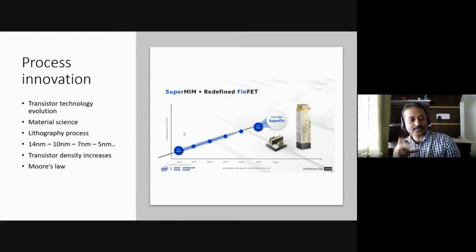So as you know about Moore's law, which says that every 2 years the transistor density doubles, right? Let's say if you have 1 billion transistors in a CPU now, after 2 years it will be 2 billion. But then the CPU size will be the same. So that means we have to reduce the size of each transistor or gate by half, or roughly around that. So that's what this 14, 10 nanometer evolution says. So these individual transistor gates are reduced in size. They go into smaller and smaller nodes, and it's not that easy.